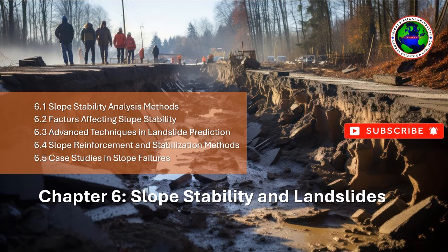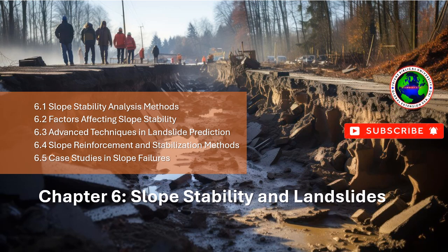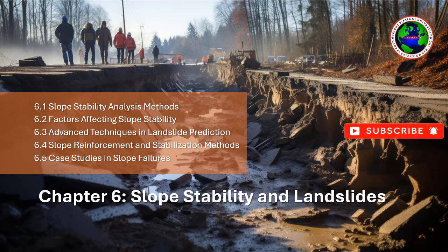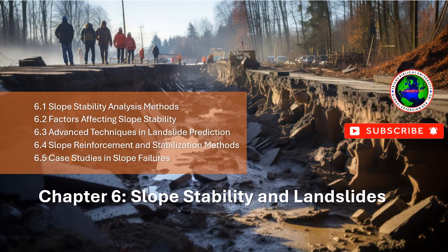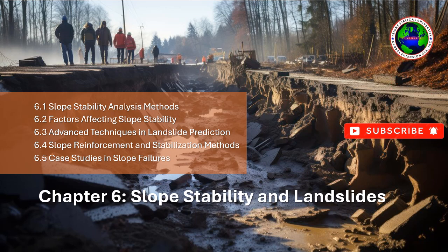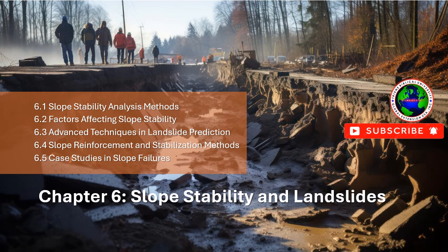Advantages: effective for stabilizing steep slopes with limited access. Minimal disturbance to the existing terrain and vegetation. Cost-effective for moderate to severe slopes. Applications: stabilizing embankments, cut slopes, and hillsides prone to erosion or landslides. Used in tunneling projects and excavation works to prevent slope failure.